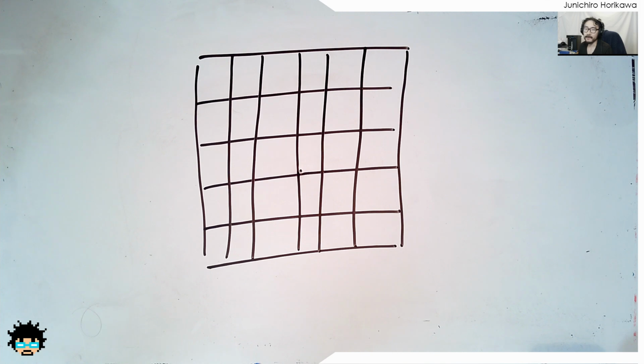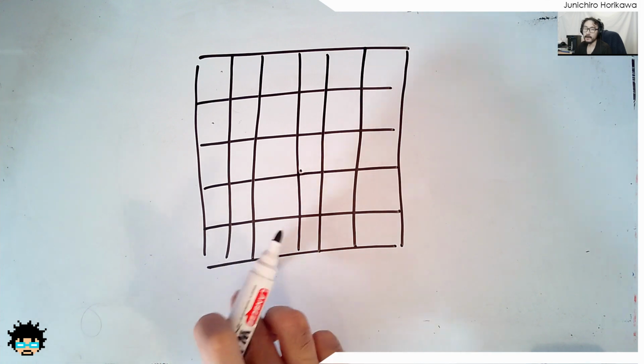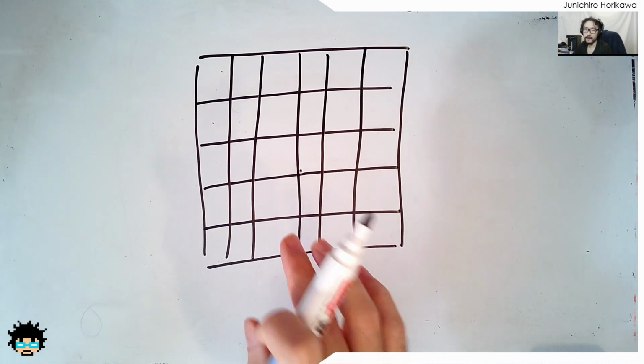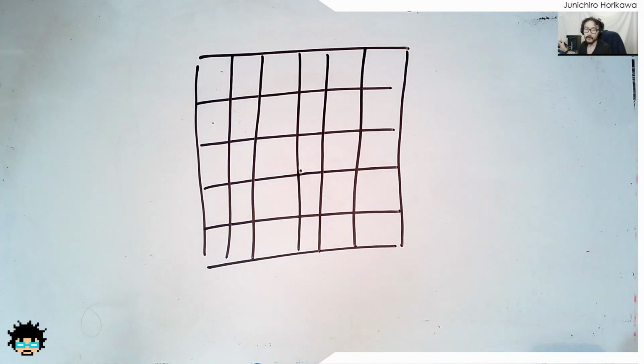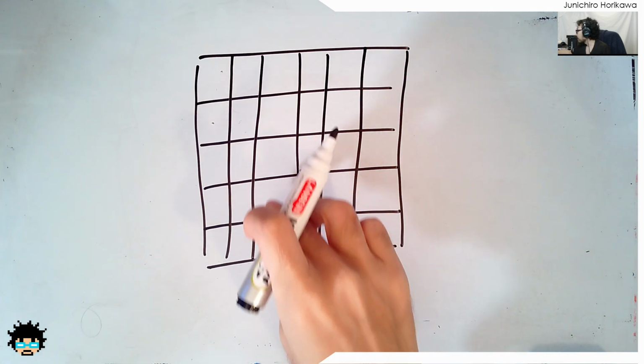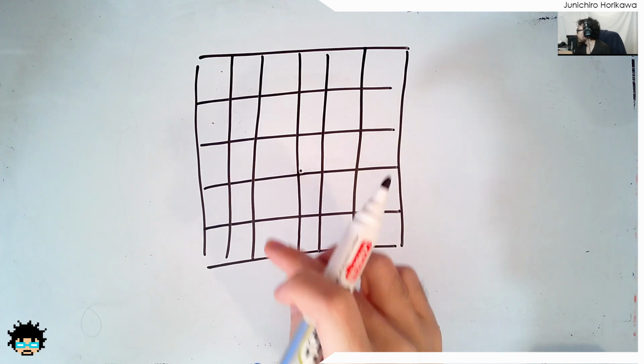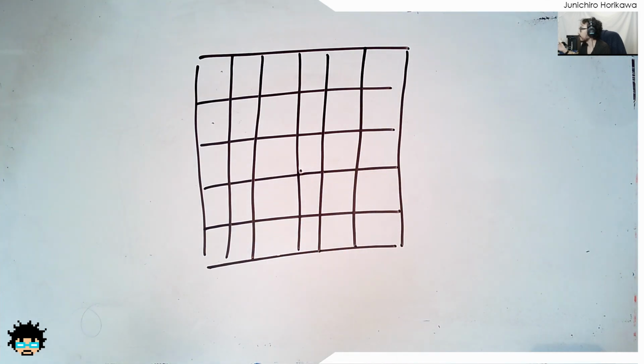And in most cases, this seed value for the noise is a location-based value, such as position or an attribute in Houdini. Let's say you have a 2D grid like this and you want to use the center of each cell as the seed for the noise function. And here's the reason why the noise is called gradient noise. That is because when the locations used for the seed are close enough, then the values are also going to be close. The closer the distance is, the closer the value you get out of the noise function using the location.